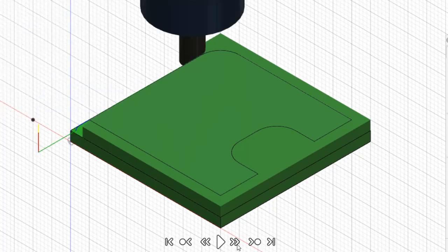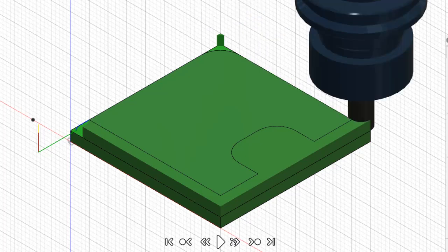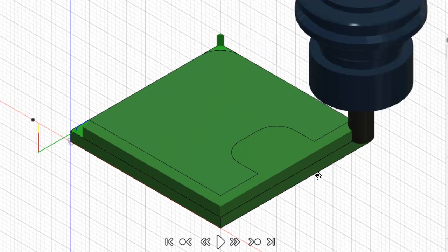The part comes along, cuts along this backside of the part, does a radius, and then cuts this straight edge, and then cuts this corner. And you'll see in a moment here that this corner is actually a radial movement. Although you could do this in a straight motion as well, you end up getting better results if you move in a radial motion around sharp corners.